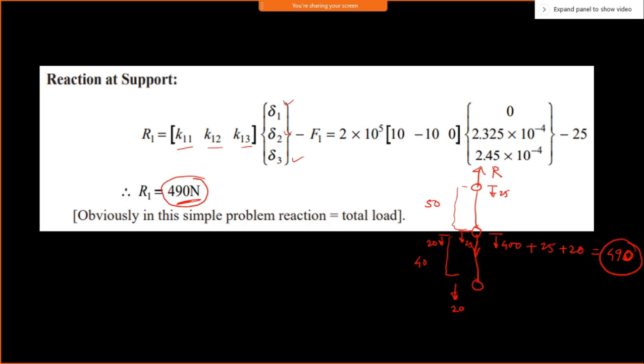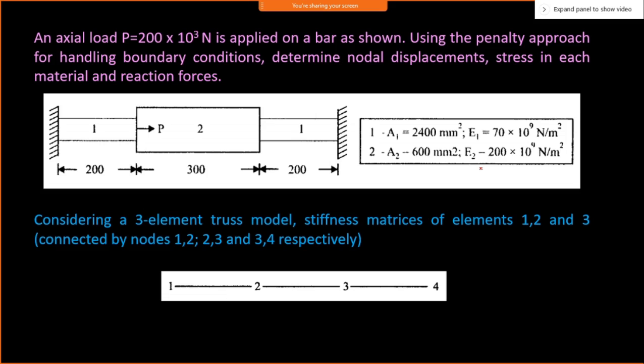That is called displacement convergence. And there are a few more convergence criteria, like energy convergence, strain energy convergence, and many more, which we'll look into in detail when we solve a problem in ANSYS.